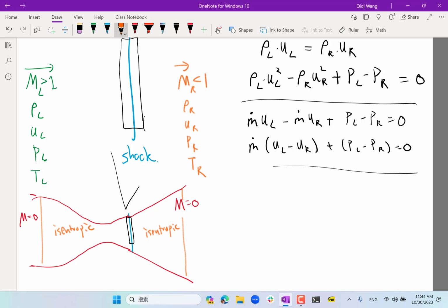We know that if there is a sudden pressure change, there is probably also a sudden temperature change, right? The air gets compressed suddenly. So when there is a sudden temperature change across a tiny region, there is going to be heat transfer, right? And as we're going to see, there is also velocity change. When you have velocity change across a small region, the molecules between the two different regions cross each other due to thermal motions, and that transfers momentum also. So you cannot assume the shock wave is isentropic. All right, but we are assuming both upstream and downstream, we shape the geometry so that we have isentropic flow.